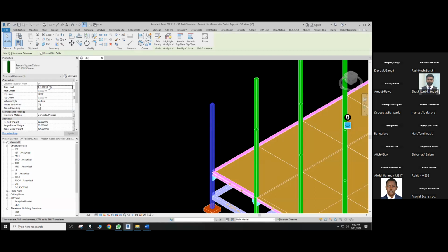So we can modify the element. To modify an element means, for example in AutoCAD, to change the property. You people know AutoCAD very well, right? If you select a wall or a column or a beam in AutoCAD, what does it mean? Change the property. What is the property? It is nothing but layer, color, line type, line weight. These are the things in the property change.